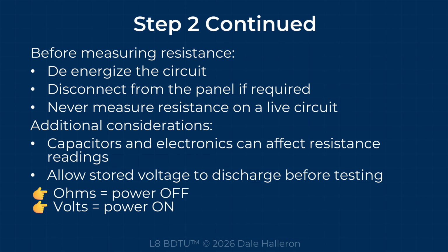Before measuring resistance, de-energize the circuit. Disconnect from the panel if required. Never measure resistance on a live circuit. Additional considerations: capacitors and electronics can affect resistance readings. Allow stored voltage to discharge before testing. Ohms is power off, always. Volts you measure with power on.